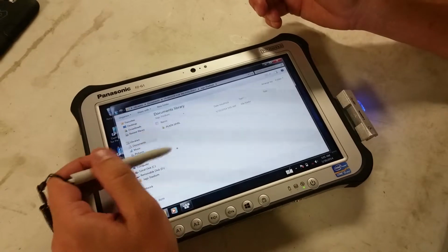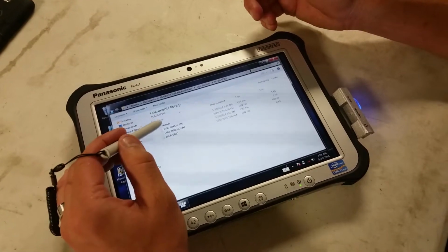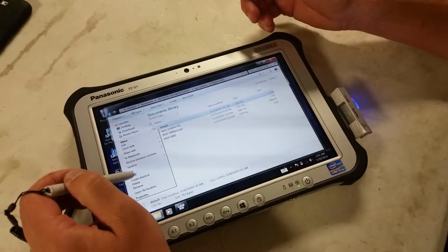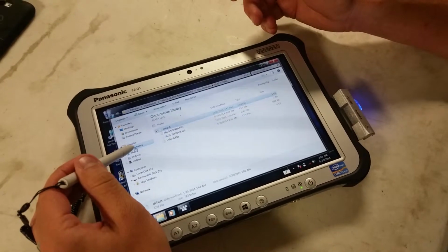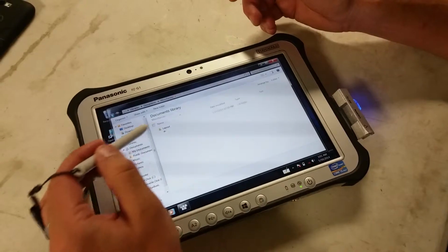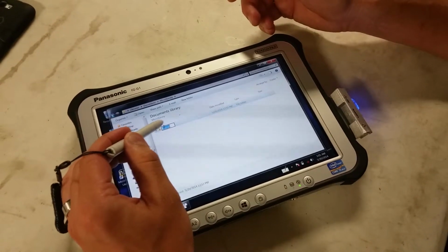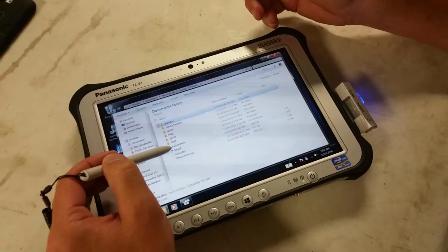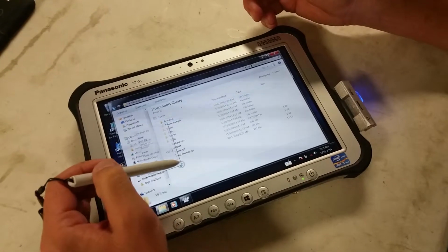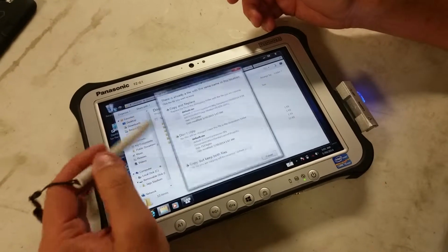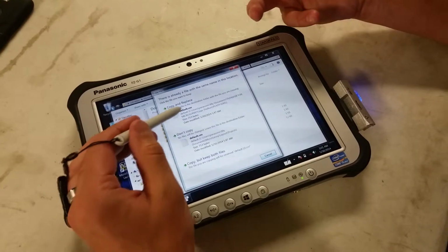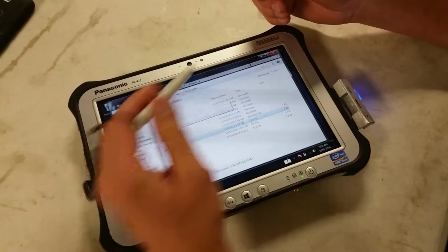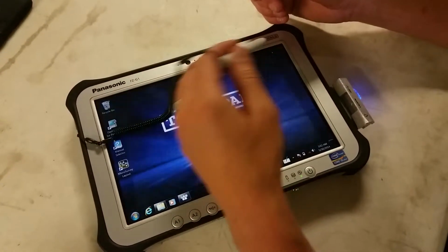Now that it's pasted in here, I can open this up and go right to my default folder and hold down and hit copy. Go to Documents, Microsurvey, Layout, Projects, and I'm going to see my default folder right here. I want to hold down and hit paste. That is updating my information, so I want to hit copy replace. Now it's updated in the software with my new point, so I can close this out.